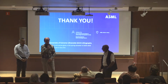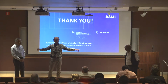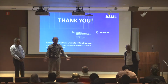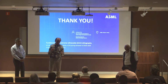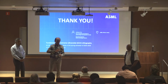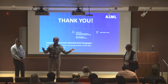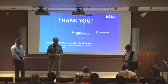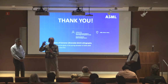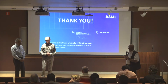Yeah. So let me first answer that question. You're absolutely right, and perhaps I wasn't completely clear. Remember that video where we picked some clips out of this huge design, right? Those clips were supposed to be representative proxies for the incredible variety of patterns of the whole design. When we optimize the illumination, we co-optimize that with the OPC for those clips. But we cannot say, let's co-optimize the whole design with hundreds of billions of patterns together with all these variables in the illumination and with all of the variables in the projection optics. That simply computationally is not yet feasible. So what we do is we take some of these clips, there we co-optimize, then we say, now this illumination, since it is good for the most critical patterns, will be good for all of the other patterns, and then we do the OPC, a divide and conquer strategy. Once the OPC stage, you don't change the design anymore.